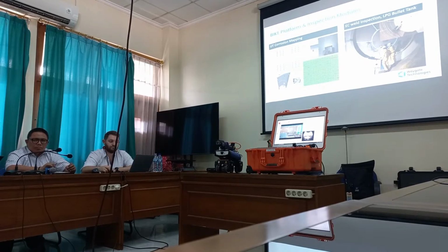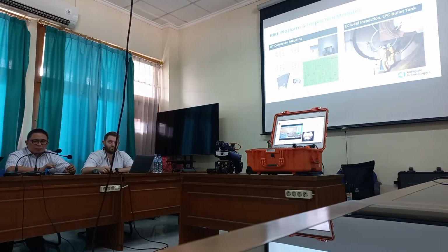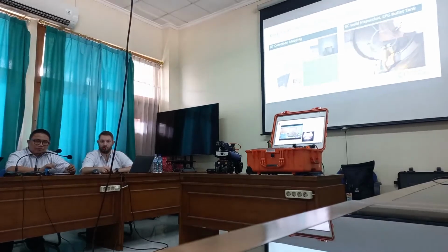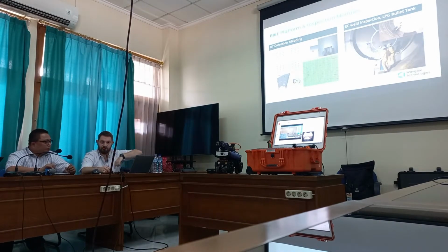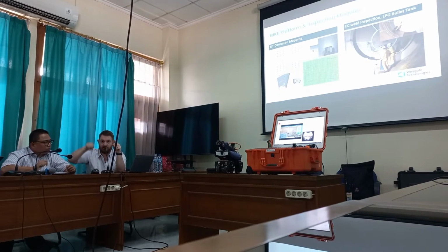Yes, it's programmable. We can choose the length, the distance between the scans, and then how wide we want the total scan. So we can say we want the scan to be 300 by 300, and then every 5 millimeters or 10 millimeters, we want it to take a reading. And when we set up and we start to play with the robot, I'll actually show you, and we can have it do that on the floor. Hopefully there's enough traction with the tiles that it works.